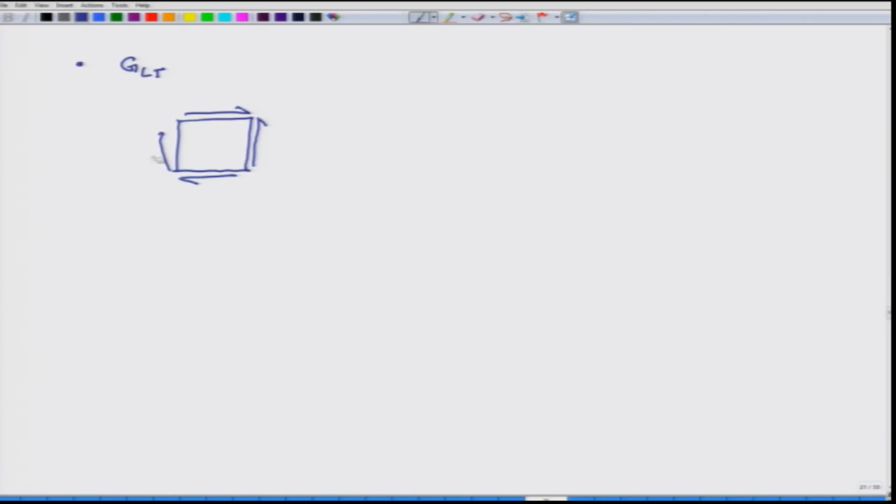So, this you can do either on a rectangular slab, but it can be more easily done on pipes and you can subject them to torsion. So, that is much more easy to do. So, you subject it to shear stress tau LT. The fibers in this case are again aligned to the L direction, and because of this the sample undergoes some shear strain.